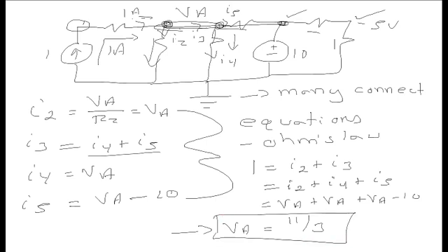Believe it or not, I'm now done. I know all of the voltages across my resistors, and through that, I can use Ohm's law. Now, let's see what those voltages are, because the voltage across one of those resistors is actually backwards. VR2 and VR3 are the same, because they are in parallel.